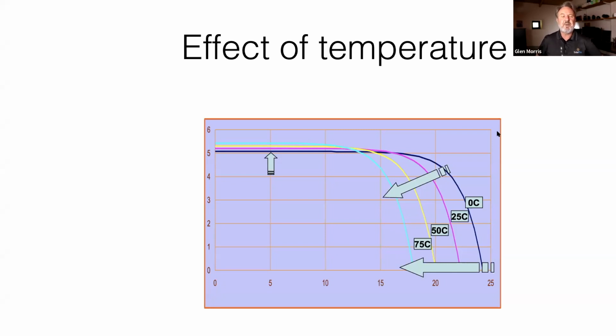I just assumed that a bifacial was basically as good as a monofacial, which means there's a back sheet on the back, so only light from the front can be useful, and therefore bifacial at least as good as a mono. But I'm told by the experts that actually that's not true, because there is a certain amount of bounce within a solar PV panel from the back sheet back into the module, into the cell, sorry. And so when you remove that back sheet in a bifacial module, unless you have some bounce coming back off the surface that's beneath it, like the roof, you may be worse off.